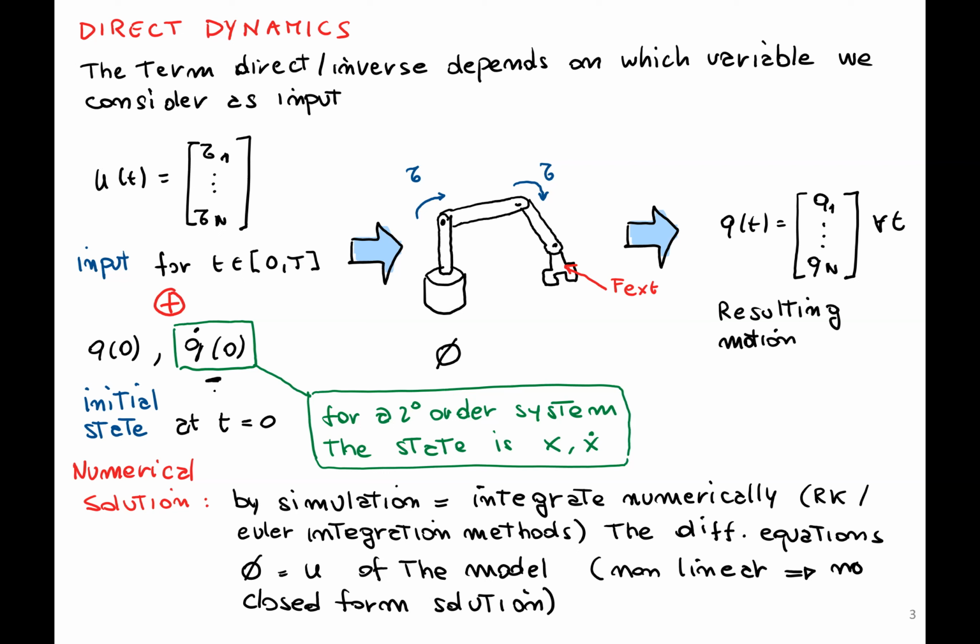So we see what the maximum acceleration is, and we can tune the size of the links according to their weight and their inertia, and we can play around with simulation.